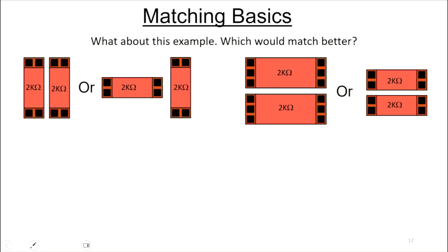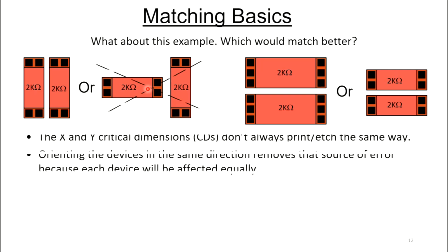How about this one? We have 2 resistors oriented in the same direction and 2 oriented in a different direction. I think, again, it should be pretty obvious. If you're trying to match, you orient them the same direction.